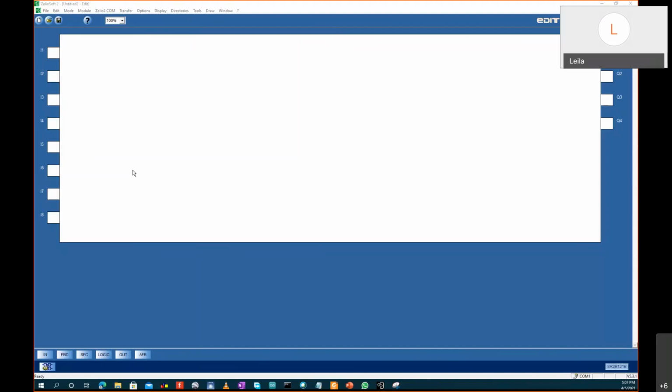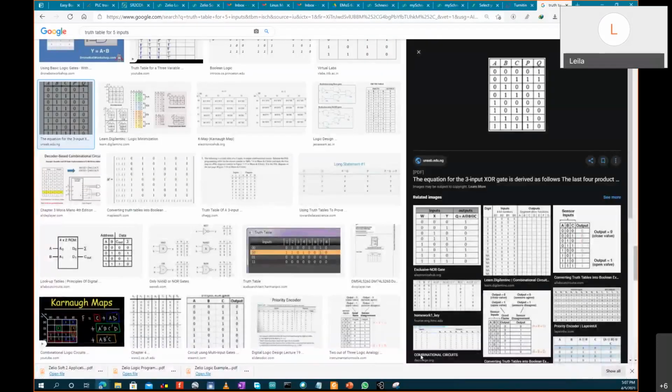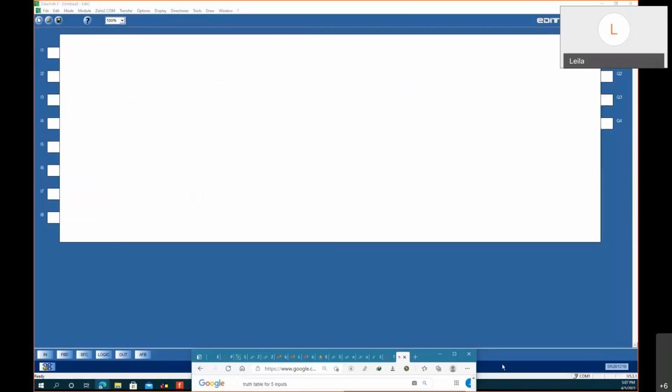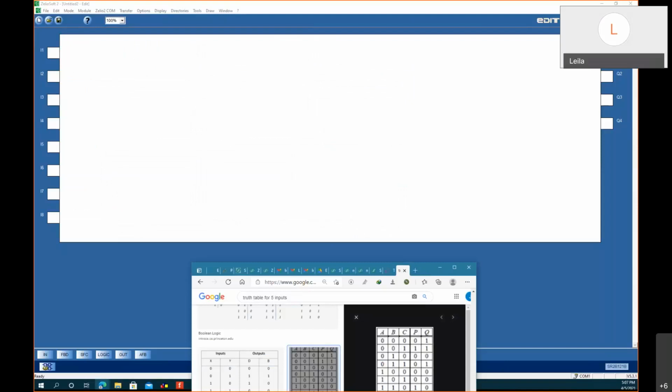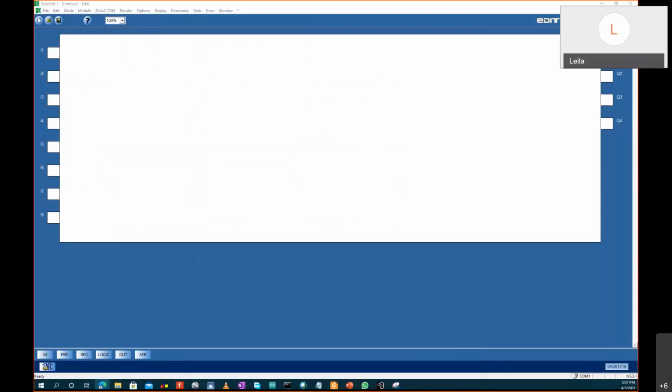And then so that after the 5 seconds are over, it will close, and then it will activate timer 3, which is now the timer that's going to time for how long the green is going to be on, which is 14 seconds. Okay. And then the last rank, which is like for amber, and then the sequence continues, like goes back to the beginning.